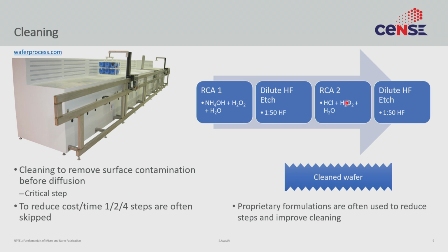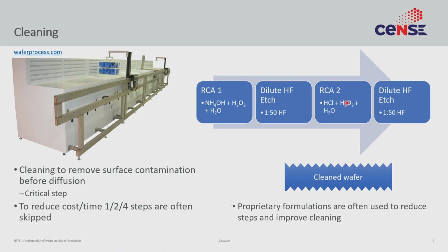It depends upon what sort of contamination is there in your process, what contamination exists on your wafers, how clean is your system, and how little of a cleaning is enough for you to not create so many defects that it affects your efficiency. So it's all about a very cutthroat, very careful cost-benefit analysis. Okay. This is what a wafer cross-section would look like. Nothing has changed. You still have the pyramids, but now the surfaces are clean.